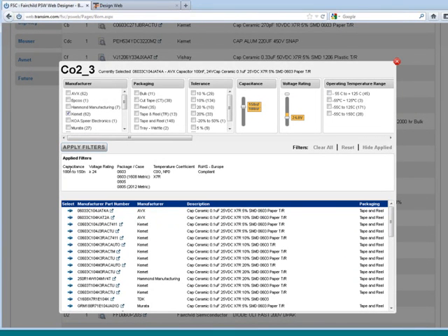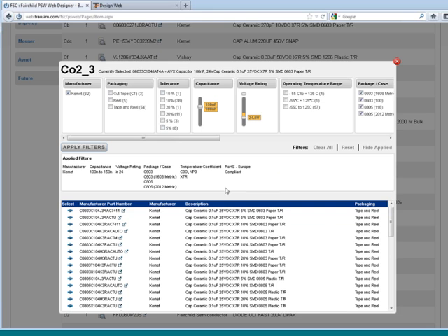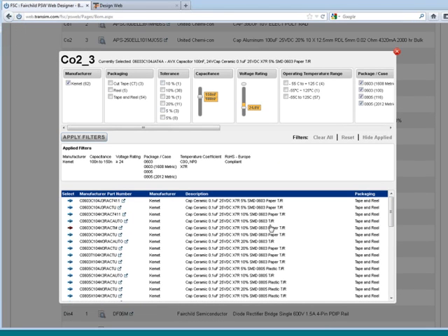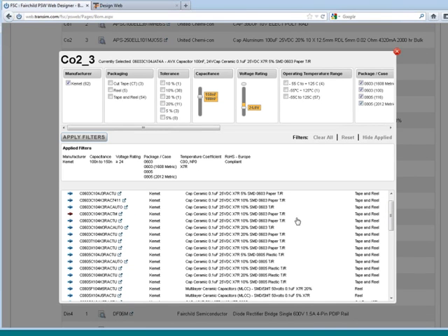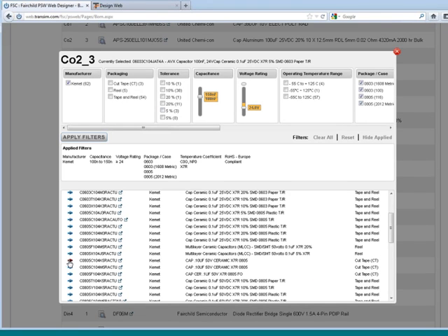So right now, the rules that the application engineer has set up are basically these rules. So he said he's looking for components that are between 100 to 150 nanofarads, and that will change based on your design parameters. Because my design requires a voltage greater than 24 volts, I want to focus on 0603s and 0805s, and I'm going to pick capacitors based out of this material, and of course I want to be RoHS compliant. But I don't want to use AVX. I want to use only Kemet because they've been really nice to me, and I'm gonna just use the Kemet component. So if I apply filters, now what I've done is I've narrowed my selection to just the Kemet suppliers. And you remember here originally I had the AVX component. So now I can go through this BOM and say, okay, which one do I want to use? And I'm going to use this component.